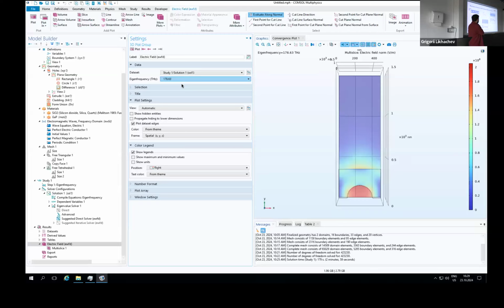But of course, you will see in the later session on fabrication that something like this will have much higher losses than something like this, because the maximum of the electric field here is still propagated in the waveguide. It doesn't see any sidewalls in the middle. Here, you have an abrupt change, and if the fabrication of the sidewalls is not perfect, every time you find an edge, it has some roughness.